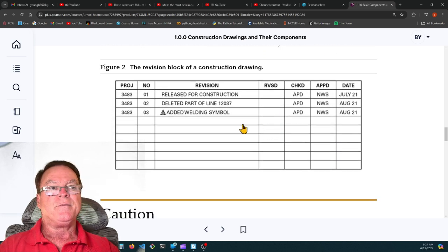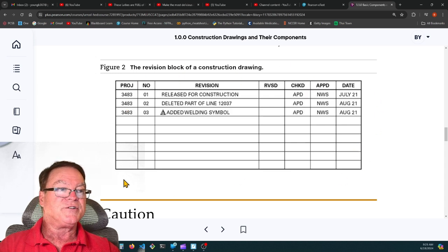So you can't put a lot of information in this one line, but they'll put a note number, this triangle, or they'll put some way of finding it on the blueprint. And a lot of times what they do on the blueprint is they'll put a cloud around the change. They literally will draw a cloud shape around that change, and they'll show what's new. Or if it's something being demoed, they'll draw a cloud around it and then draw everything in dotted lines saying, this is going to be removed, this is coming out.